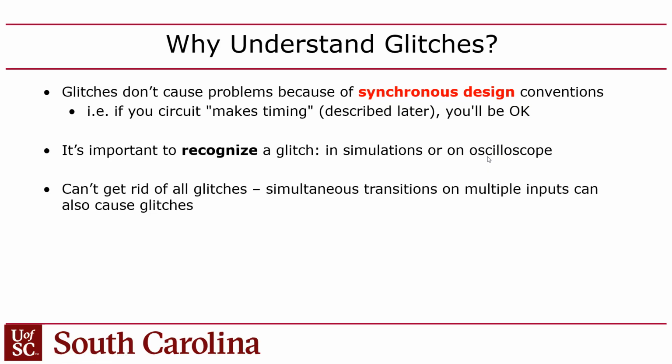Now, as you mentioned, glitches don't really cause a problem if you have the logic in the middle of two registers, two flip-flops that are clocked, right? The idea is that we don't really care if there are glitches, because generally the glitch is going to happen in between the contamination delay and the propagation delay, right? So by the time the propagation delay elapses from the time you change any input, the glitch will have worked itself out.